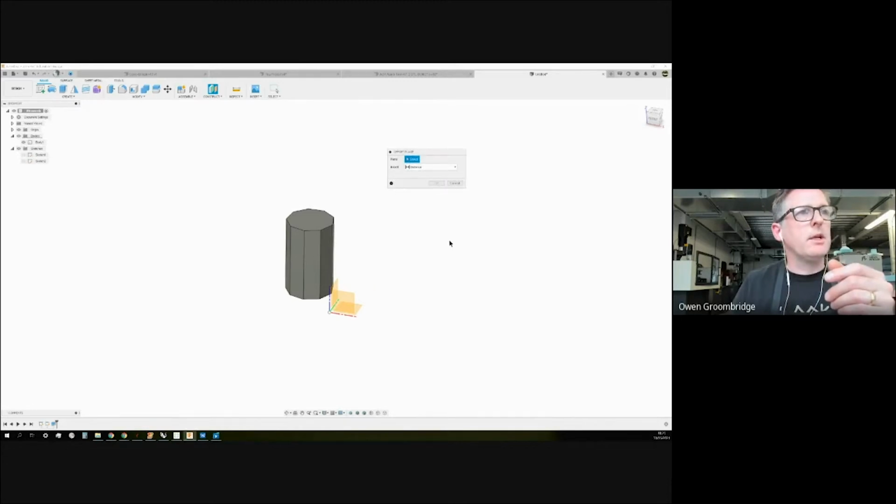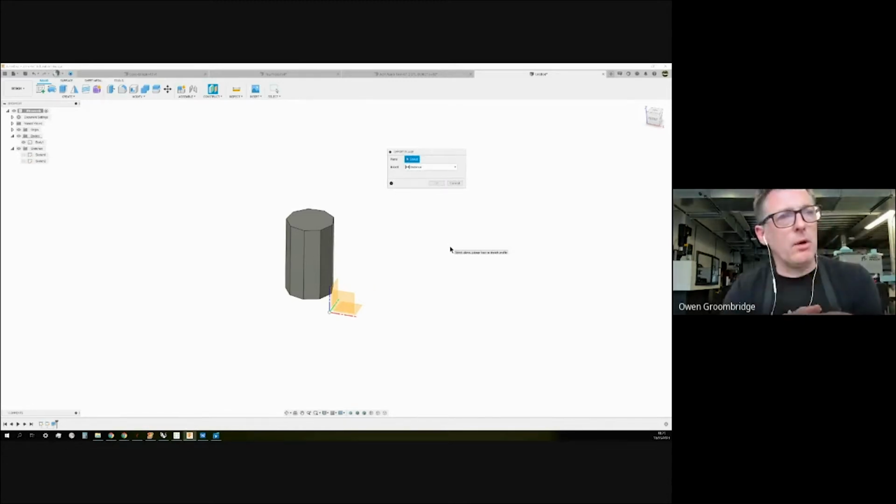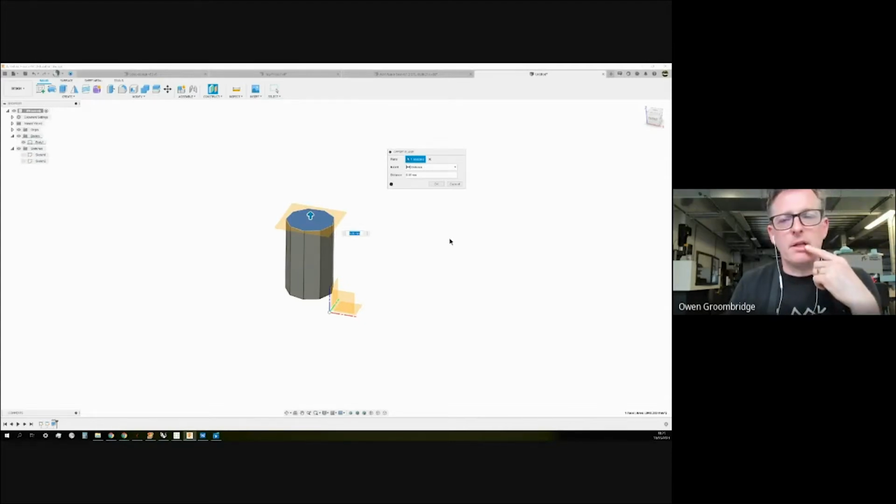Now the thing is, you need a starting point to begin with. It says select plane. It's lying. You don't have to select a plane. You can select a surface. All right. Boom. There you go. I've instantly created an offset plane from a surface. All right. With which I can move independently. Notice I can only move it perpendicular at a right angle to that plane.